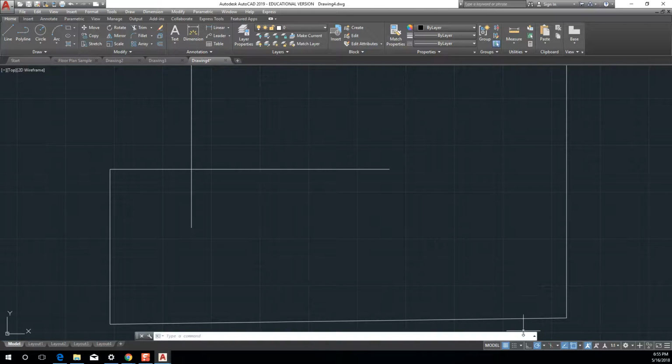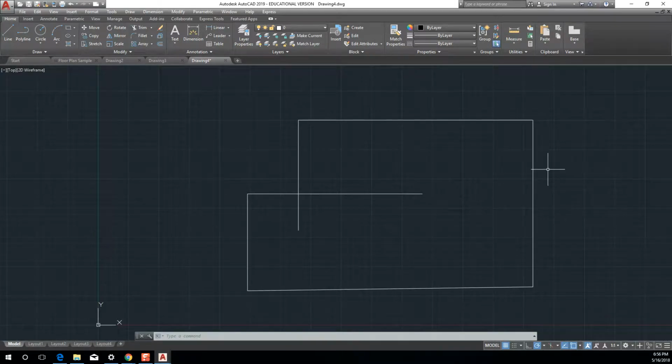So for example, this little icon right here is called ortho mode. The way that I know that one of these icons is functioning, it's turned on, is it's blue. If it's blue, it's turned on. If it's grayed out, it's turned off, okay? All of these are also somewhat automatic, meaning when they're turned on and I go to draw something in model space, they just kind of pop up when they are needed, okay? So you don't have to click on the icon and then do something to make it work. It just sort of automatically works. So for example, I have ortho. Now today is one of those just watch what I'm doing, and we'll get into these more a little bit later on.